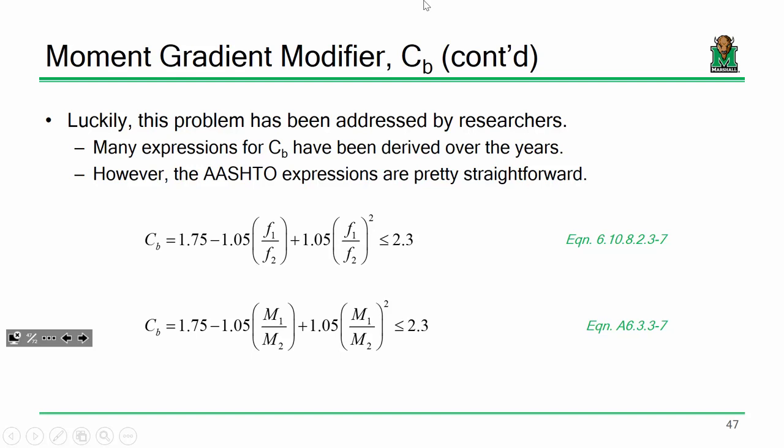They're a little different than the ones that we use in the building spec, but all in all, I think they're a little easier, especially given the fact that when we're dealing with bridges, we're not dealing with moment and shear diagrams, we're dealing with moment and shear envelopes.